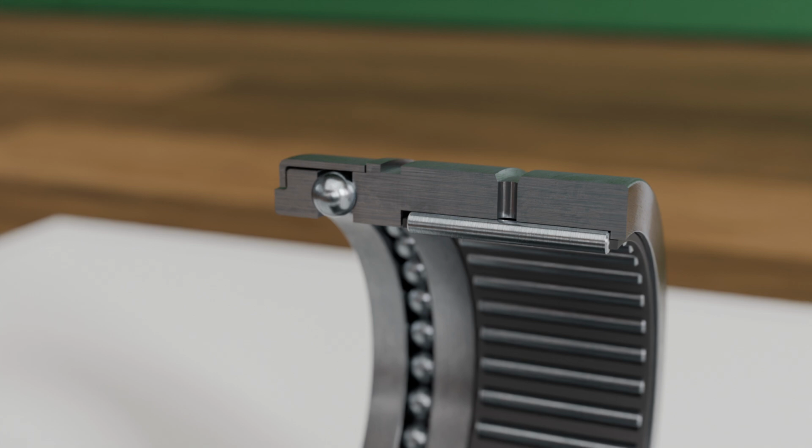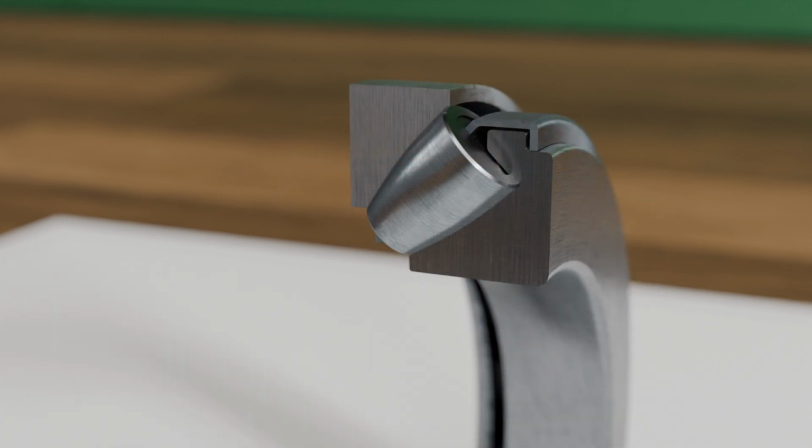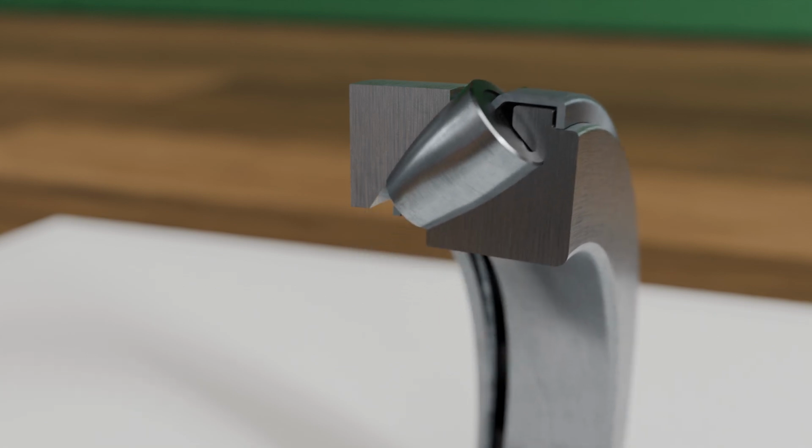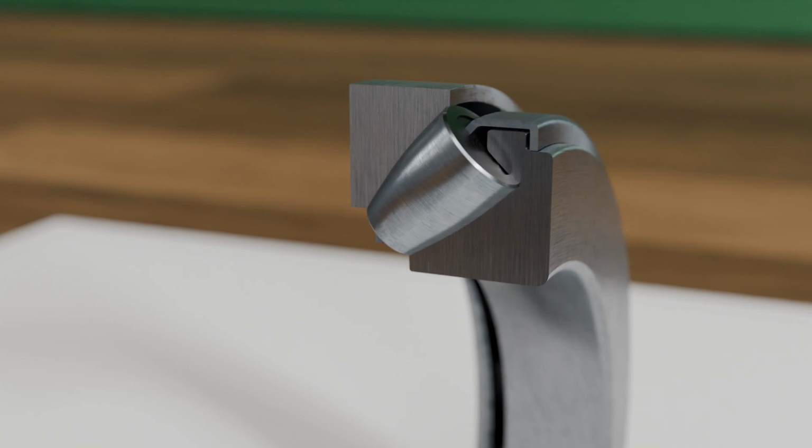Another type of bearing is the spherical roller thrust bearing, which can absorb high axial forces in one direction and also withstand radial forces. Its characteristic self-aligning function is achieved by a spherical raceway in the housing, allowing the bearing to compensate for angular misalignment between shaft and housing. It consists of rollers guided in an inclined cage. It is typically used in applications with high axial loads, such as heavy-duty presses, ship drives, or conveyor systems.